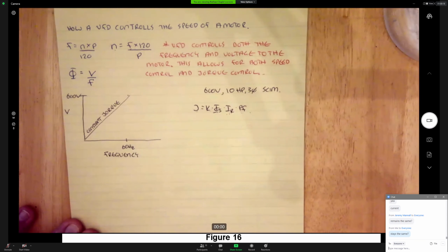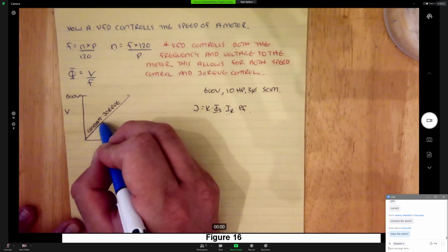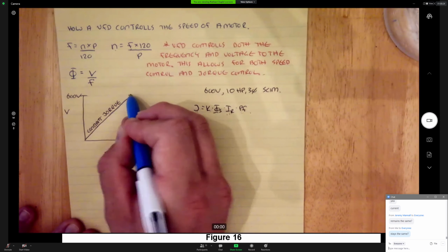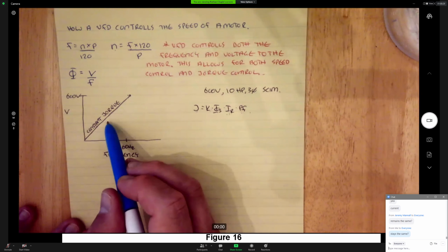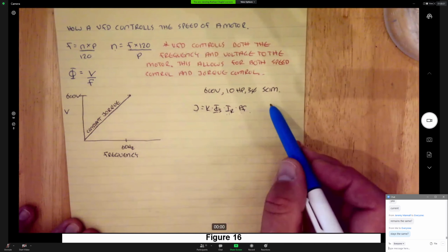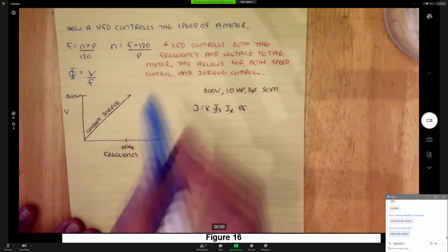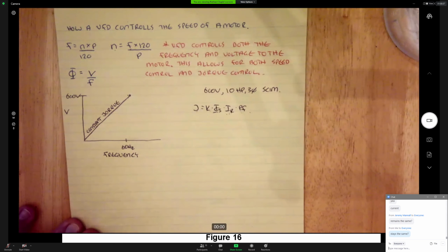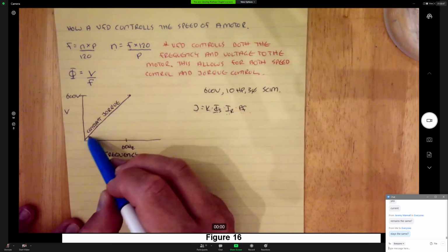And it's measurable, very measurable. So long as we are increasing voltage and frequency at the same rate, that motor is going to make a constant torque, which means there aren't any big dips in starting torque and pull-up torque and breakdown torque. And the translation mechanically is that you're going to have smoother acceleration and better control of your connected load with a constant torque right here.